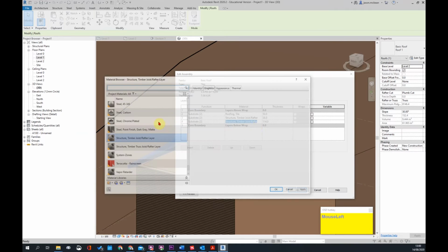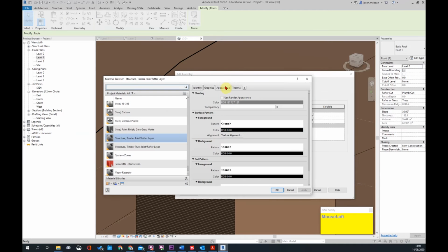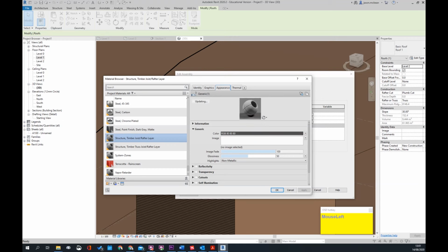Okay, no, it doesn't like it. It didn't get the whole layer. So here I just want to edit this material quickly. I'll explain this in a second when we use the override of the line material, but generally you want structure to join with structure, and substrate to join with substrate. So if another roof had to join this, it's just how they join. You give layers a hierarchy so that a structure will always join with structure, and a substrate will always join with substrate. I'll show that when I draw a section of wall as well.